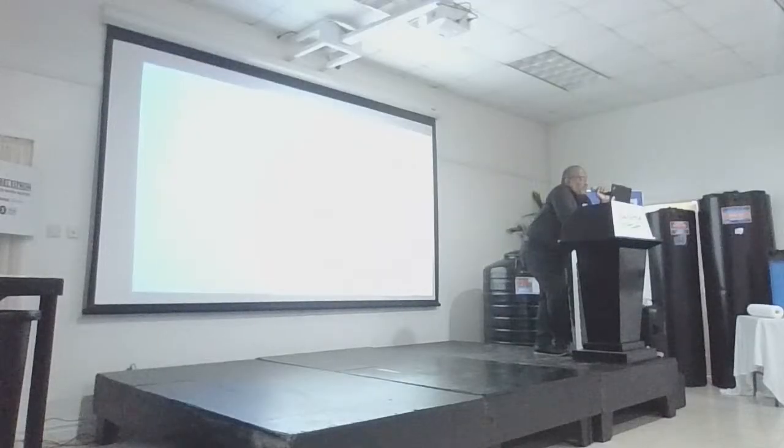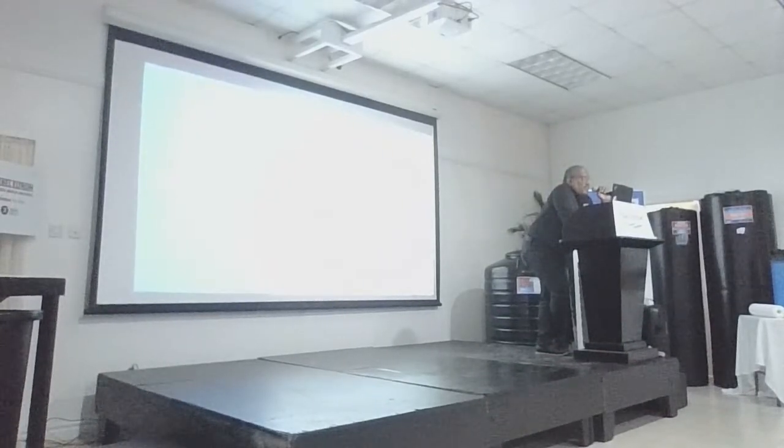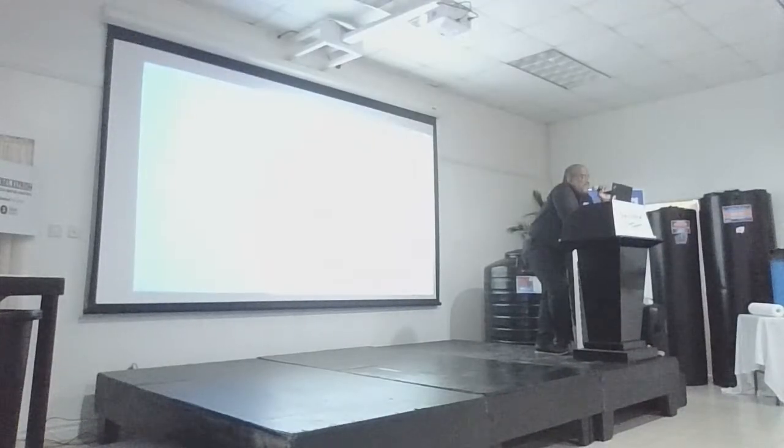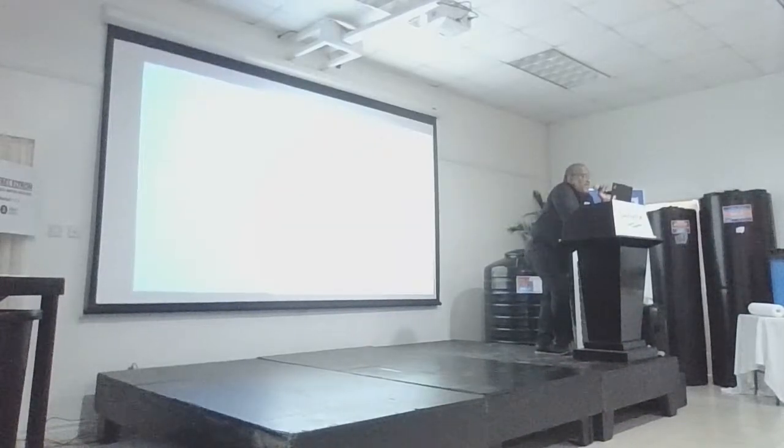So I did a rough sample here of the 750 gallon, which is authorized for 12 users. Now, the 50 gallons a day is just a figure I put in, assuming flushes of water by a person in a day using 50 gallons per day. So you get a retention time of 1.25 days.